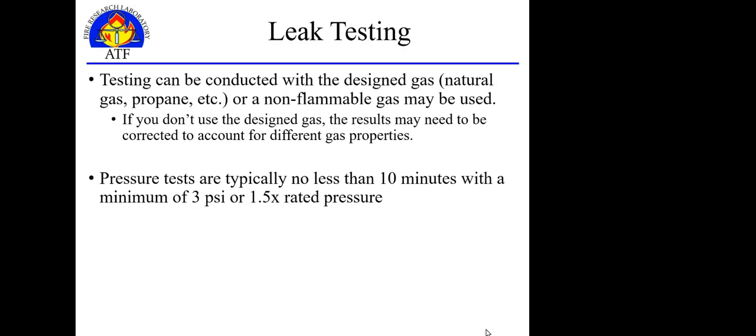Typically you can use the fuel gas, as long as you can do it safely, or you might use something like compressed nitrogen, or just an air compressor or something like that. If you're using something other than the fuel gas, you have to account for the different gas properties when it comes to your leak rates.